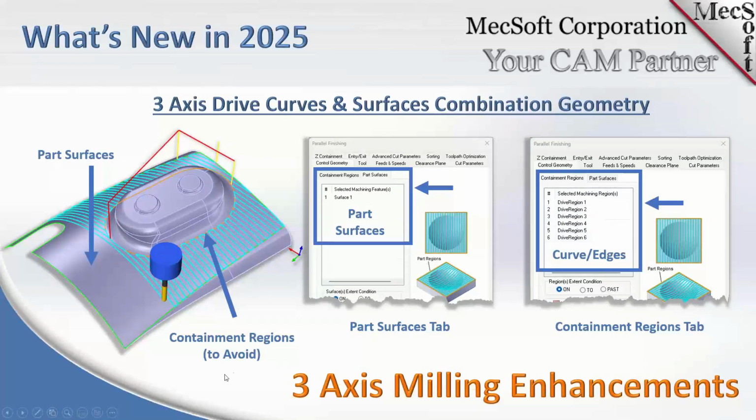Okay, here's an interesting one. In 3-axis, we provided the ability to use both surfaces and curved regions. And when you do that, similar to the way in 2-axis operations where you have a nesting perimeter, an outer perimeter and an inner perimeter, the toolpath is actually between the two.